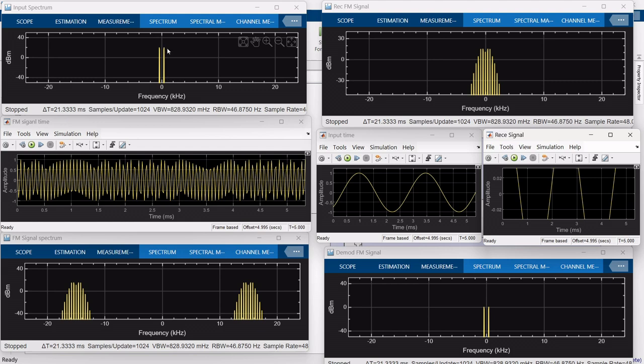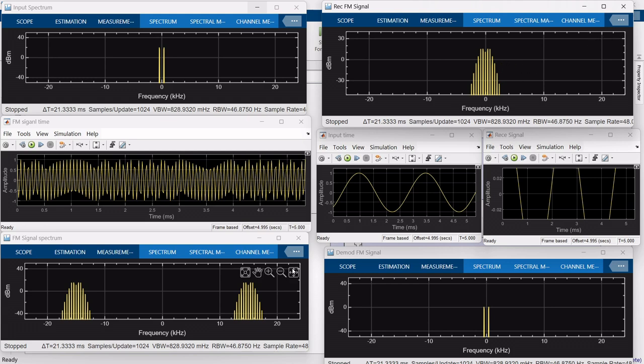So simply we have an impulse at 400 Hz. This is the frequency modulated signal in time domain. This is the frequency modulated signal in frequency domain. We notice that we have here the carrier, which is 15 kHz, and we have the signal centered around the carrier. So this is after multiplication by a complex sinusoid, which translates the signal from 15 kHz to baseband, to 0 Hz.